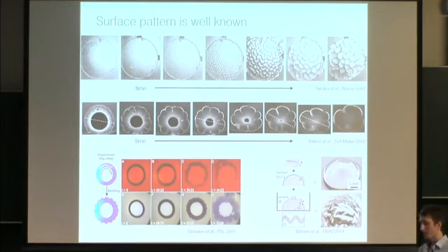And the reason it happens is actually kind of intuitively obvious. When you put a gel into water, the outer layers of the gel are exposed to water first, and they want to grow in order to bring more water in, but they're attached to the inner layers, which have a harder time getting to the water, and which are still rigid and small. And so the outer layers basically bulge on top of the inner layers, and this generates the mechanical instability. And that goes away as the water content becomes uniform within the gel. So this is exactly that phenomenon in a variety of different contexts.